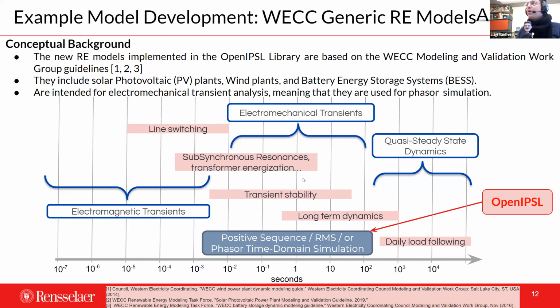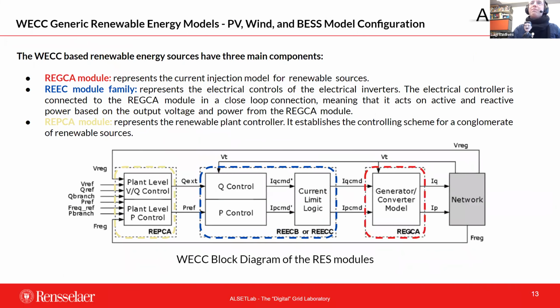So the library will cover basically subsynchronous resonance, transformer energization, transient stability, small signal stability, voltage stability, and every type of analysis that you typically do with those tools. Based on the guidelines published by the WECC, we implemented this model. This picture is exactly the same as the block diagrams that we have in PSSE.